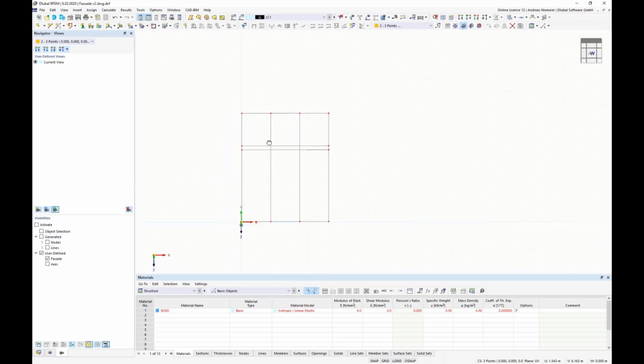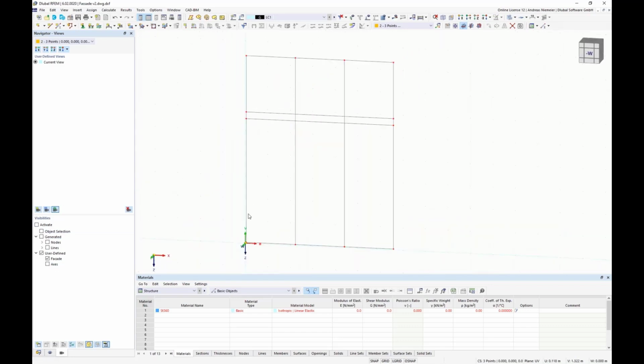So now we know exactly how big the facade is, what the dimensions are, and what the grid spacing is, and we can go ahead modeling this structure. For this, of course, we take a closer look at this model and see that the draw of this facade has lines from left to right drawn over these mid elements. This is not really suitable for RFEM because you have to define some contact definitions. So we repair it with this intersection function and create single lines.